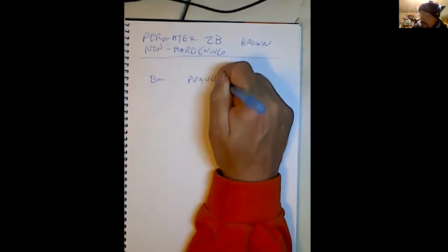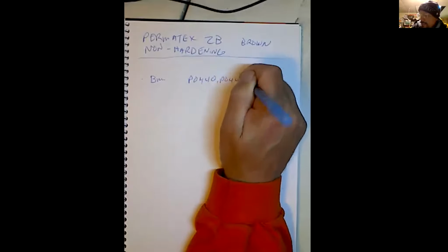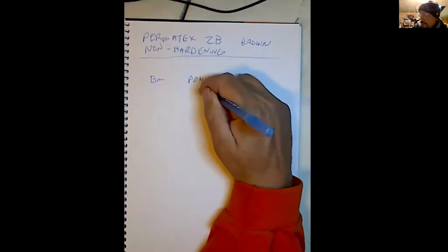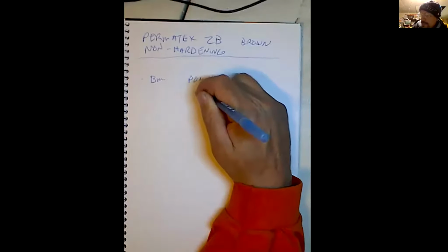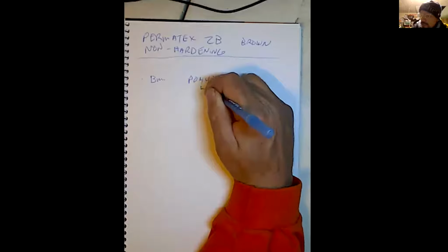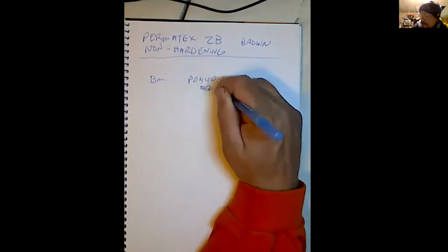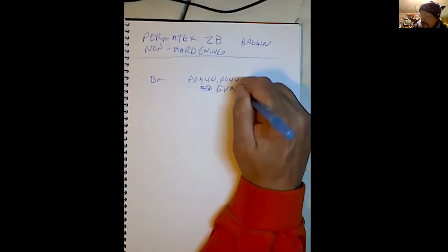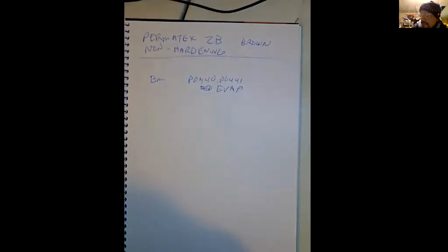As it turns out, the code was reading various things, one of which was evaporative emission system purge control valve circuit open, and evaporative emission system incorrect purge flow.